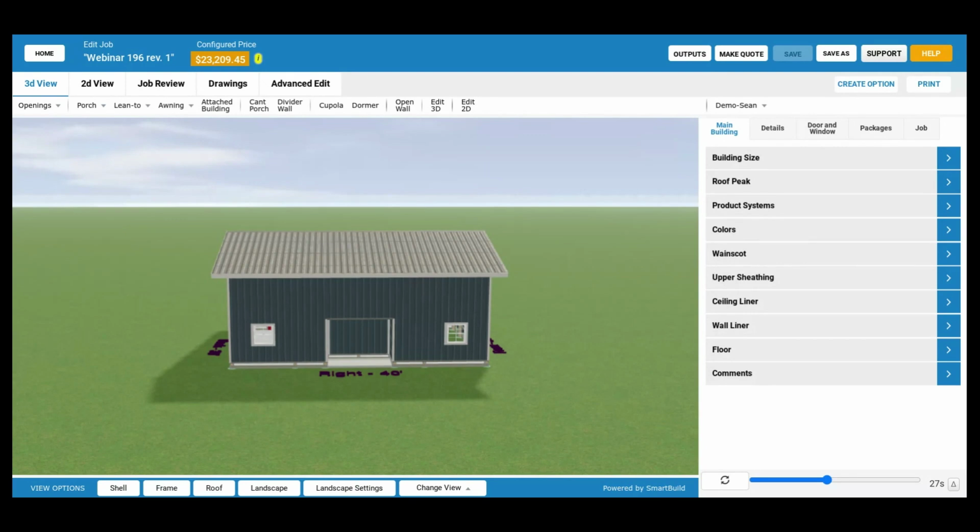If the zip code is this or this or this, use this other loading. So instead of a user having to know that, oh, over in my neighborhood, we use 50, 10, 0, and 12, they just have to know what their zip code is. And that will get the correct loading selected so that it picks the right trusses, and uses the right span tables when it's looking up the materials to use for posts and girts and things like that. So people who make use of that will find that extremely valuable.